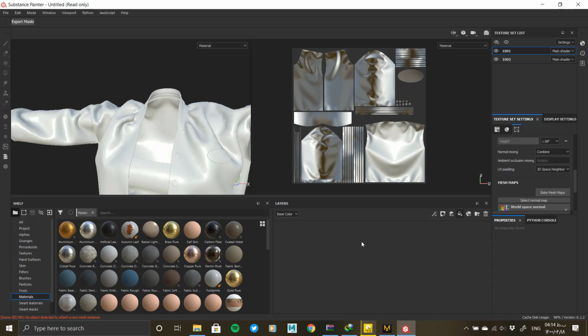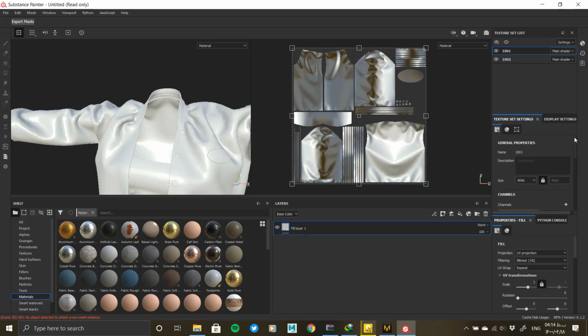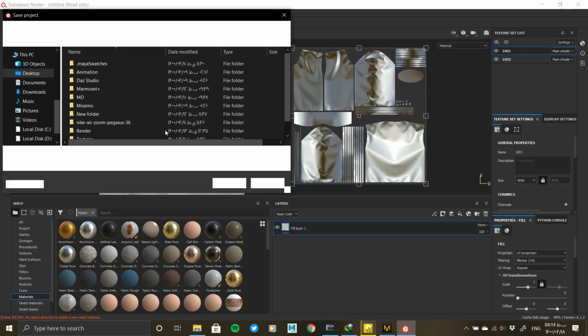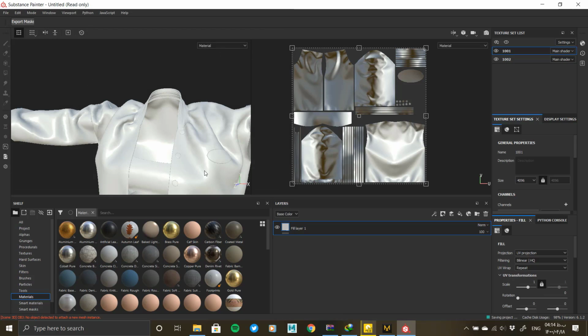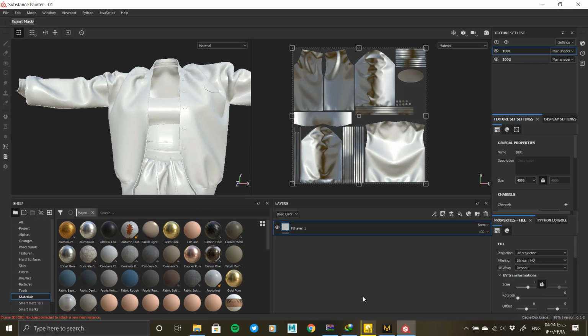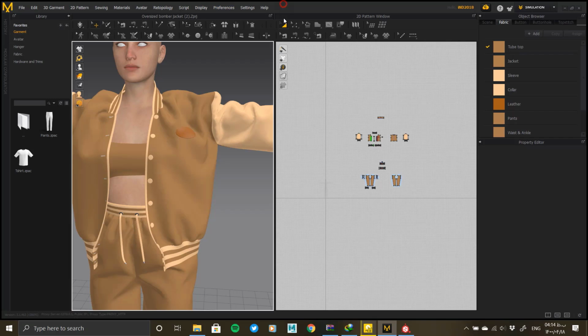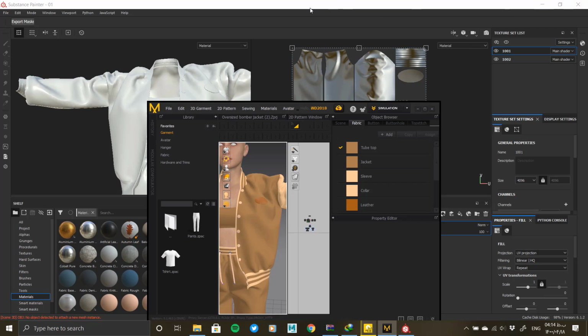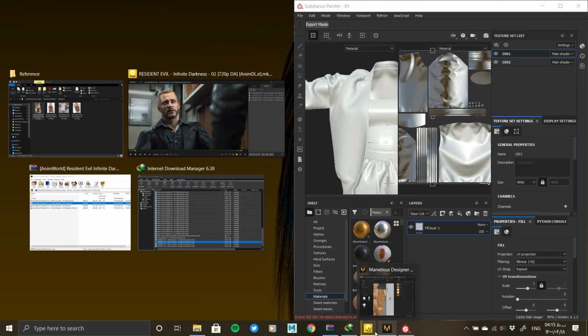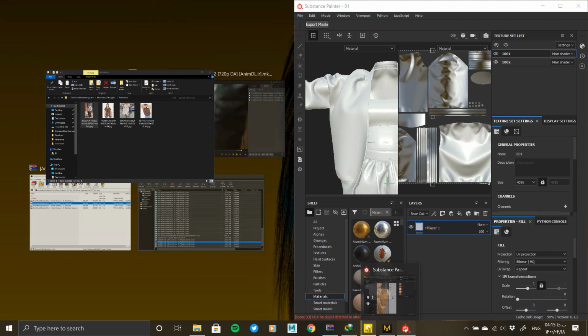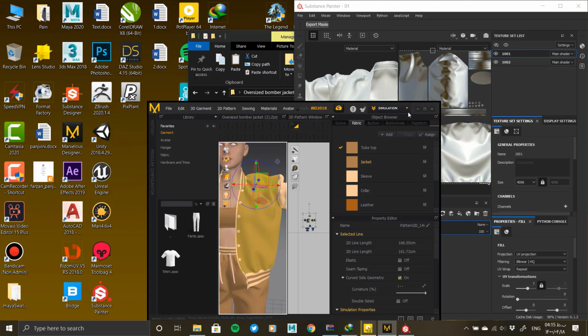After we bake all the parts, we start making materials by creating layers. We start by determining a general color for the clothes, and for more details, we can add the mask and generators, as well as the procedures, and combine them using blending modes, to achieve the desired result in producing the original color. The same process can be done for other sections. For example, for fabric details and protrusions in its layer, activate height and add a special texture, to produce the desired material. And we can make big changes in them, by using level and filters.